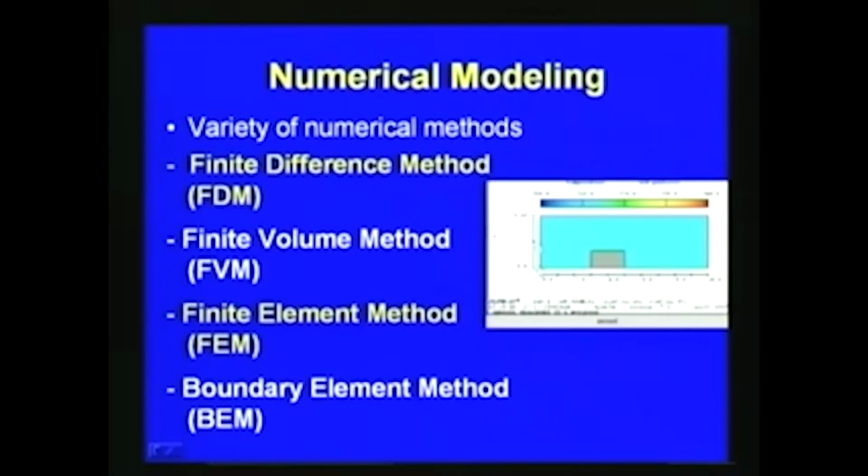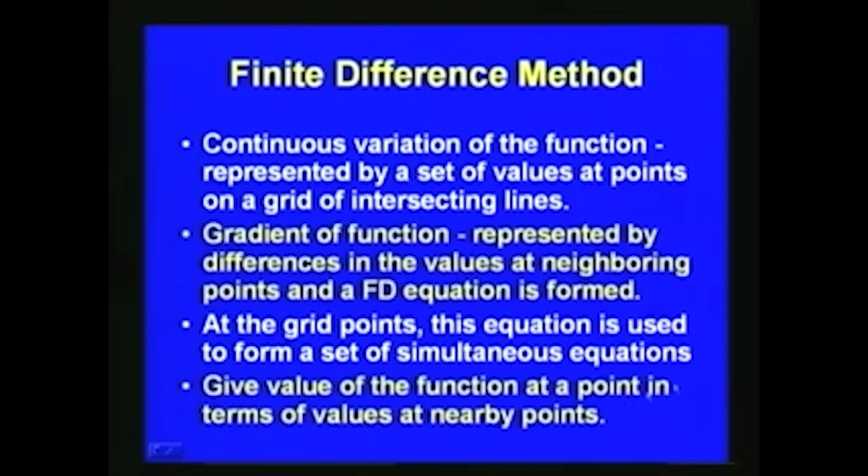Then we will be applying the boundary conditions. For example, in this figure, if we know the velocity at the location where the flow is entering, and here we will be having a no slip condition, and then the other conditions here. So, based upon the boundary conditions, we will be solving the problem.